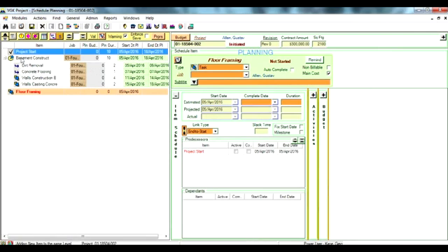Note that the item is placed on the main schedule at the same level as the project start and basement construction. Project start was an initiator and was set as the predecessor, but that's not what we want at the moment. So we want to identify that wall casting was the predecessor. So we'll simply reset it by dragging it to the predecessor list.